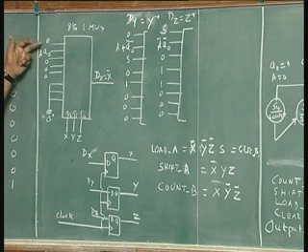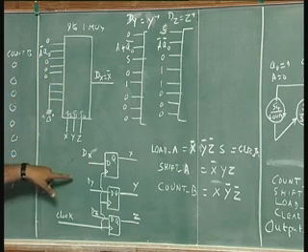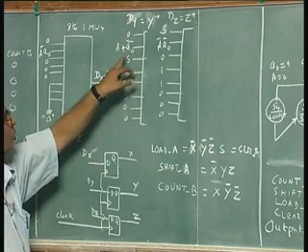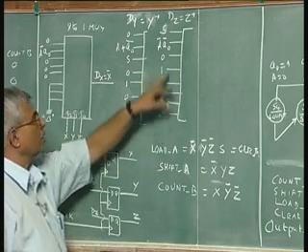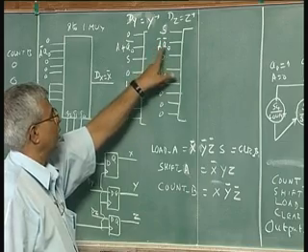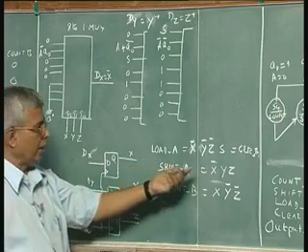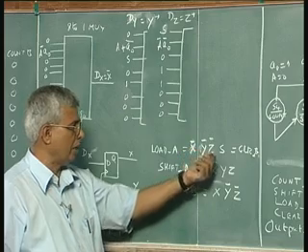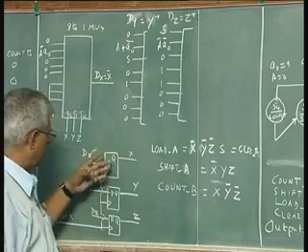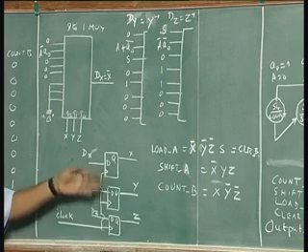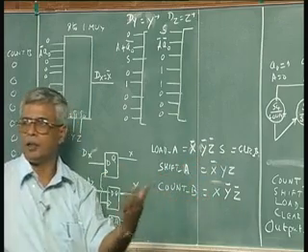We get these values. For example, first input is 0, then it is A bar, A, 0, 0 0 0, 0 0 0, etc. Similarly, for dy, these are the inputs to the multiplexer, 0, A or A, 0 bar, S, 0 1 0 0 0. For third mux dz, the inputs dz are given by S, A bar, A, 0 bar, 0 1 1 0 0 0. Outputs are very simple. There are only a very few outputs. Load and clear are the same, which are x bar, y bar, z bar, s. Shift A is x bar, y, z. Count B is x, y bar, z bar. So, we have a 3 input solution, three flip flops, each driven by multiplexer whose inputs are connected like this, and outputs can be gotten by simple gates, and we have the entire implementation.